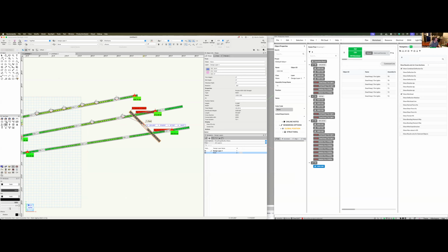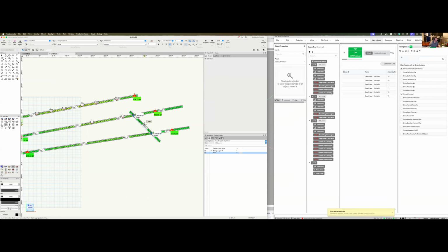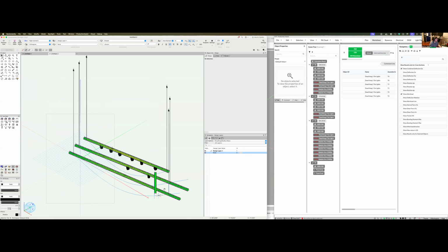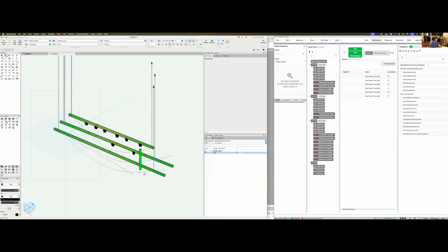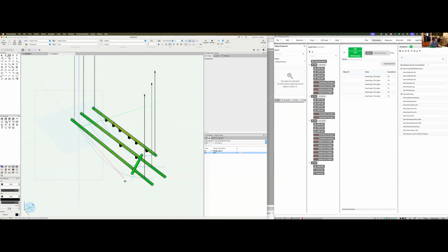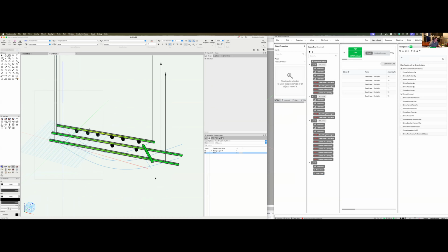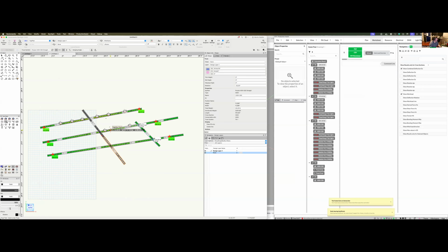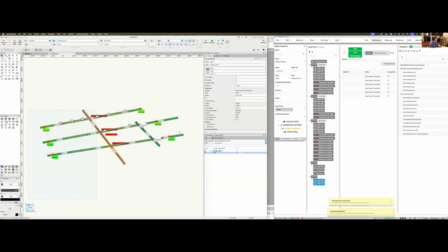Simply click on the base truss, and then on the truss you wish to stack. The tool automatically adjusts the vertical offset so that the trusses align perfectly without intersecting. This stacking process not only simplifies your workflow, but also ensures your overall structure remains safe and ready for further analysis.